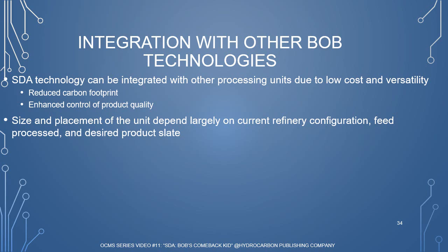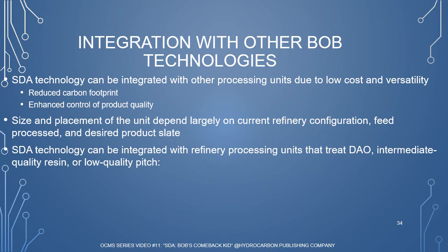Solvent deasphalting can be integrated in a number of flexible configurations with a range of refinery processing units that treat the high-quality DAO, intermediate quality resin, or low quality pitch, such as the coker, visbreaker, gasifier, resid FCC, resid hydrocracker, etc.